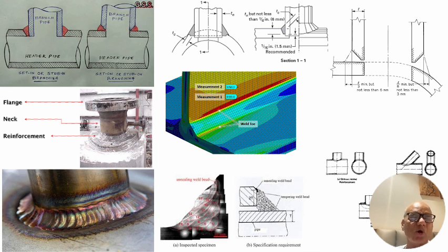There is a flange which is normally set up to the pipe before we put it onto the shell, and similarly if there is any secondary nozzle, that also is welded before we fit it, and both this flange and this secondary nozzle are the ones which are going to create a hindrance to accessibility for the welder. And then the shell radius, as you see here in this photograph, on this side of the weld you will see a good joint coming up here, but on the other side this angle is going to become quite large, and this angle is going to become less.